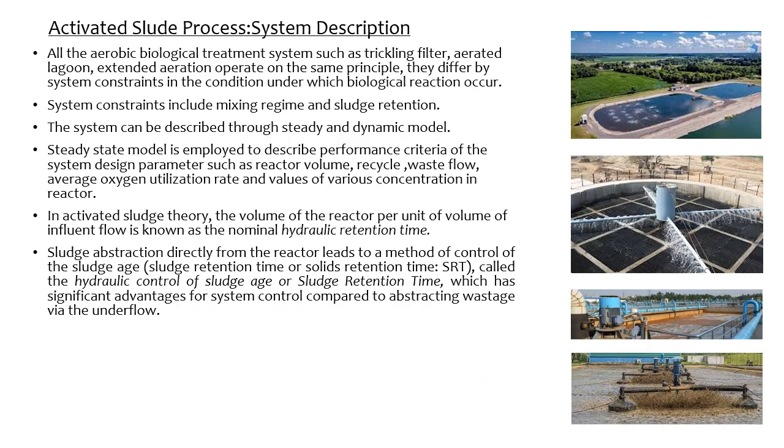Activated sludge process system description. All the aerobic biological treatment systems such as trickling filter, aerobic lagoon, and extended aeration operate on the same principle. They differ by system constraints in the condition under which the biological reaction occurs. System constraints include mixing regime and sludge retention.